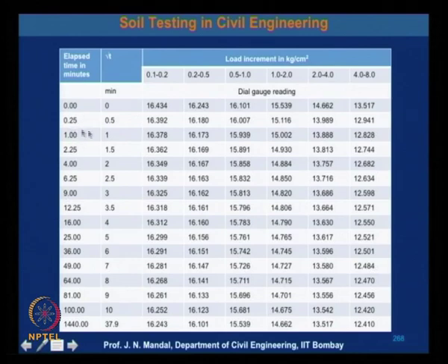Let us say at 0.25, you are taking the reading about 16.180. You keep on reading like that under the different elapsed times up to 1440, at a load increment of 0.2 to 0.5 kg per centimeter square, and this last reading is 16.101.